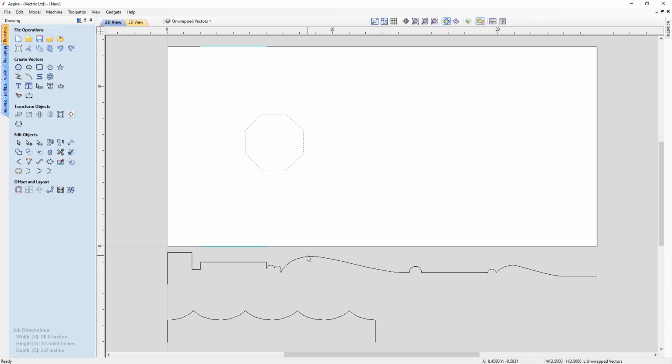Okay, so we can close out, and so we're pretty happy with the shape that we've got there for this part. But then we need to look at creating the smaller octagon. So we're just going to create a copy of this. So with that in selection mode, I'm going to hold down Control followed by the Alt key, and I'm just going to move that across. So Alt key just keeps that in line.